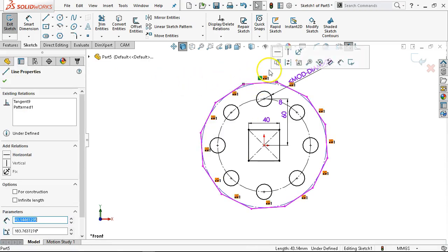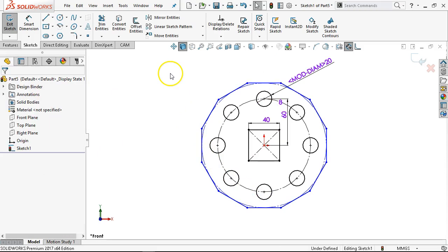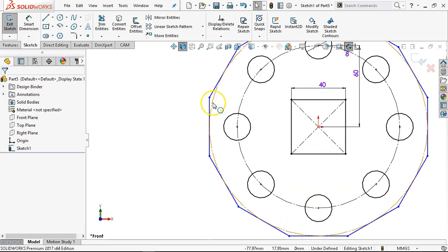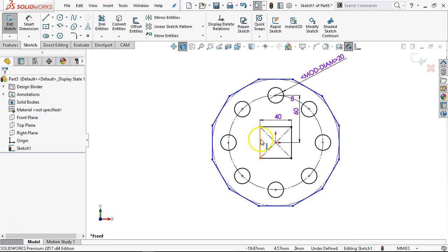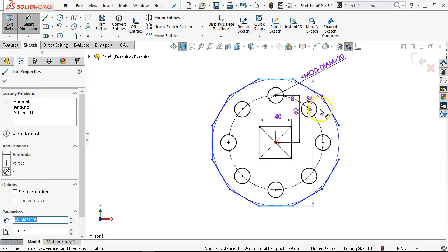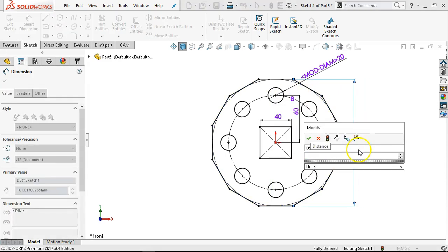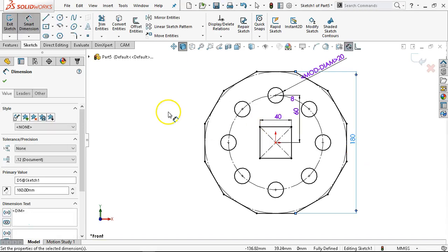It'll stay in the polygon command, so whichever line that I can grab and make horizontal or vertical, that's going to be my starting point. So the inscribed circle is tangent to the flats. The circumscribed circle is through the points at the vertices, at the intersections. All right, so whichever one we pick on the geometry, or in this case, we'll go 180 across the flats. I could have just as easily picked that circle and had it create my geometry.